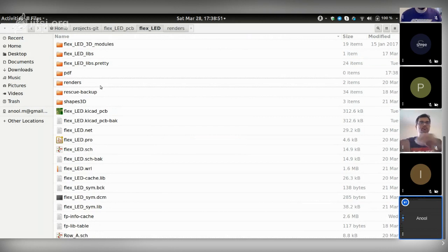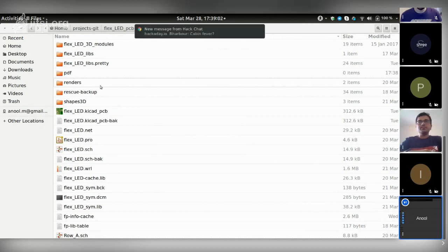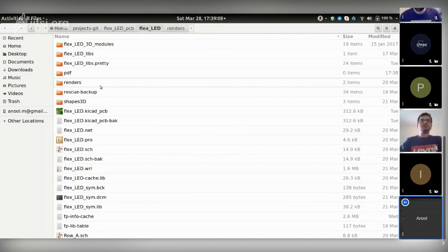That's kind of handy when you're trying to do your CAD work, making an enclosure or whatever, to have the major dimensions of your board printed out very clearly. What are the mounting hole dimensions, the spacing between holes, the size of the PCB and stuff like that, all the critical dimensions. So that's the folder structure that you set up before you get started with a project.